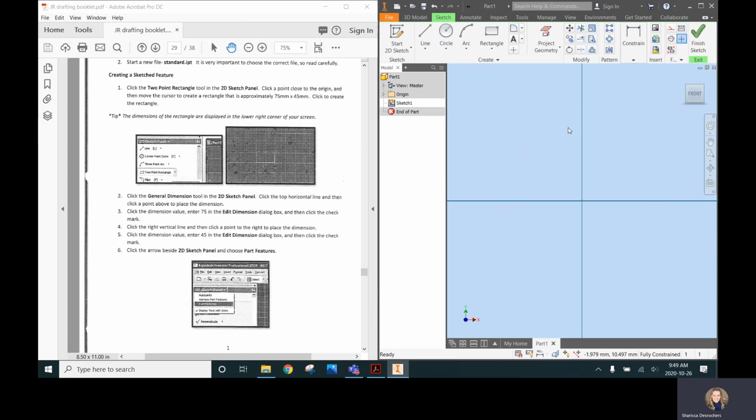I'm going to start by drawing on what would be considered the front. So that's the XY plane, or you can click the front of the cube and then click that plane. So I'm doing this so that I'm drawing on what would be the front of the object. And again, I find this less disorienting so that your preview cube matches up with your assignment. If you don't do this step and you draw on a different plane, not a big deal. You'll just rotate your project later.